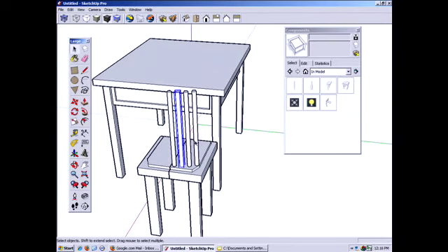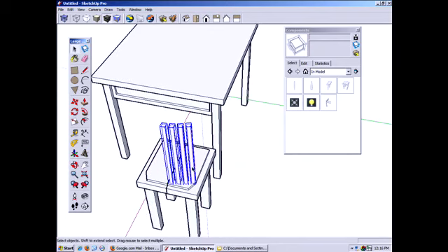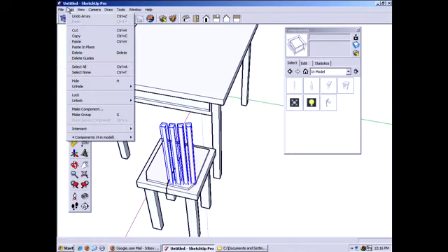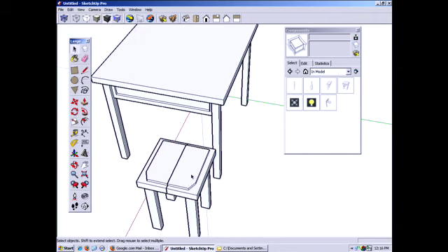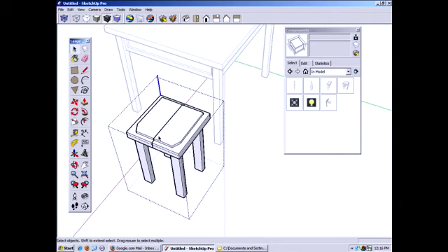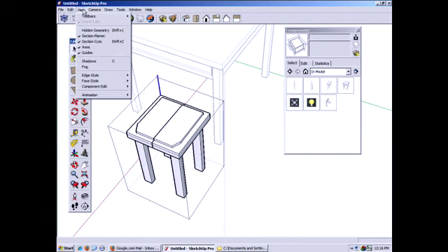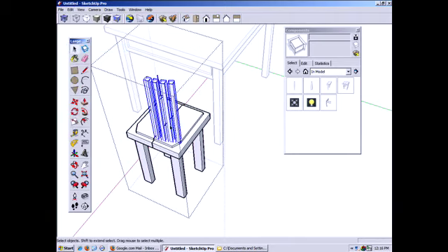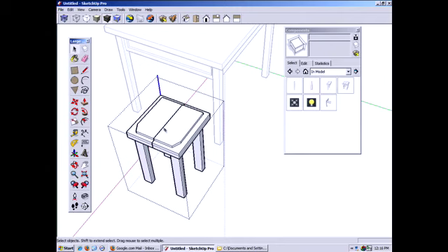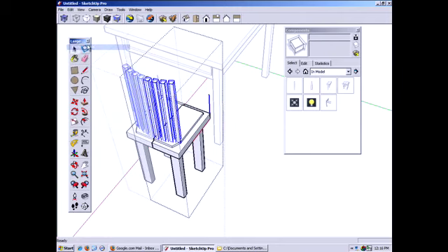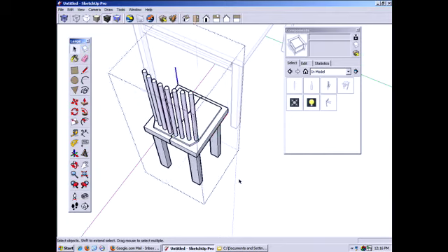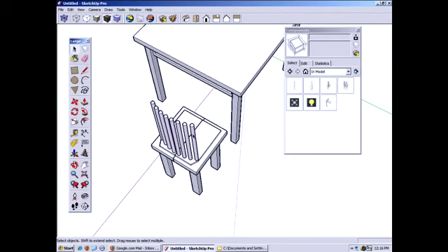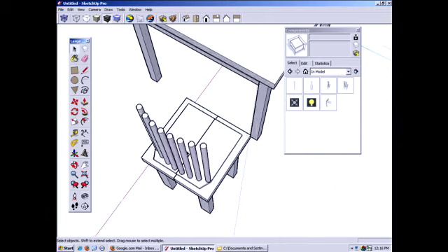Now what we can do is just select these, right? We've got these components. And again, now that we've created them outside and we haven't worried about this geometry getting on top of each other, we come in and cut those again and say, at what level do we want to place these? Well, we can't place them at this level. This is the general chair as a whole. If you paste in place here, that's not the mirrored seat, so that's not what we want. Double click again. Let's paste in place here so we get that effect. So that seems to work pretty well.